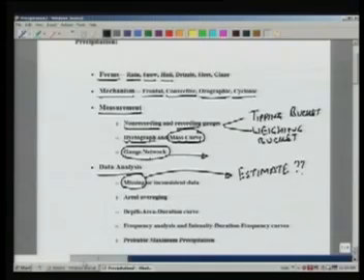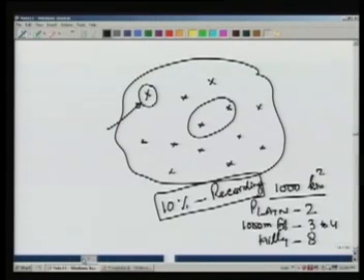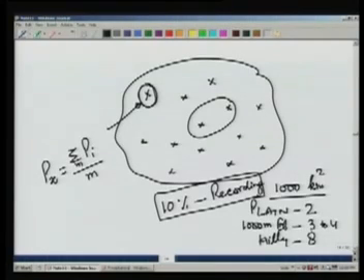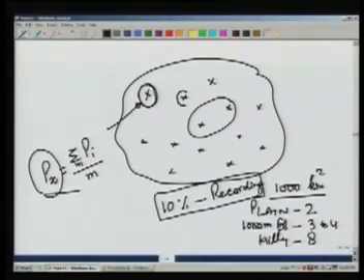The easiest thing, of course, is to see that if we have missed values at one station but we have the values available at all the other stations, we can take some kind of mean of all the other values and say that that will be the value at this point. So if we have, let's say, m other stations, then we can say that the missing value at x could be the mean of all the other values of precipitation on that day, and we estimate our missing value of Px using this. But there is a problem with this method when there is a wide variation of rain over the area. So for example, this gauge may be recording a higher rainfall than this gauge in general.